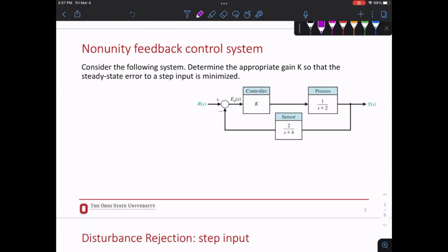All right. Now, if you add an amplifier to a system, the amplifier is kind of a controller. It does something, right? It amplifies. It can filter something or not, but the amplifier itself has a gain that can attenuate a signal. So that is a controller. But the only thing it controls is it adds gain. So if you see a block that is just a gain, that's also a controller.